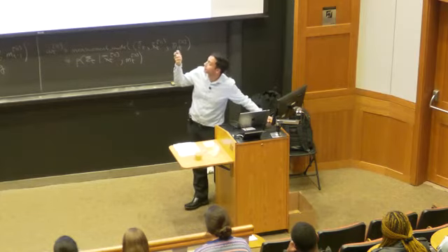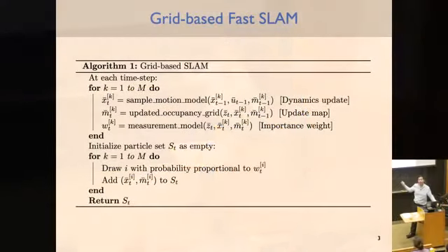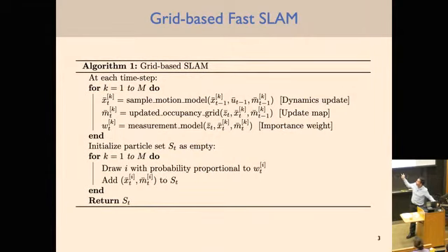What I can do is evaluate that plan for every particle from 1 through m, and then look at the sum weighted by the WT. That gives us an estimate of whether a particular plan is going to lead to a collision or not. Then we find a plan that minimizes that expected value of collisions and maybe maximizes the probability of getting to the goal. So that's another way as well.